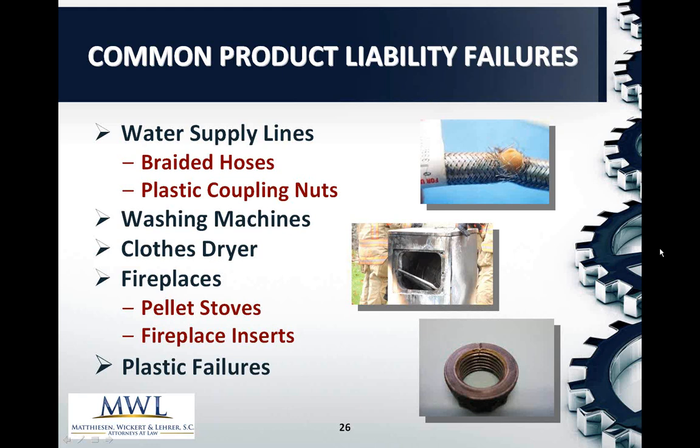In the past, they've said that, well, this nut has to be hand tight plus a quarter turn. Well, they've now backed off of that even and said just hand tight. And sometimes they warn about that, sometimes they don't. And so if it's on there too tight, it's not going to fail right away, but it's going to fail over time.